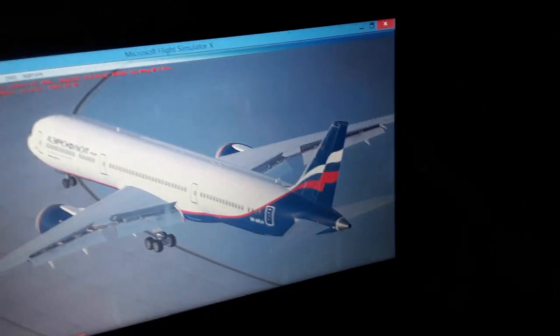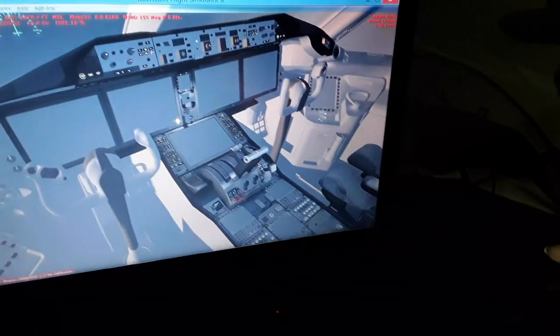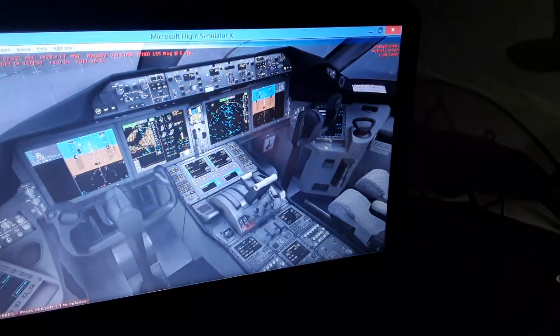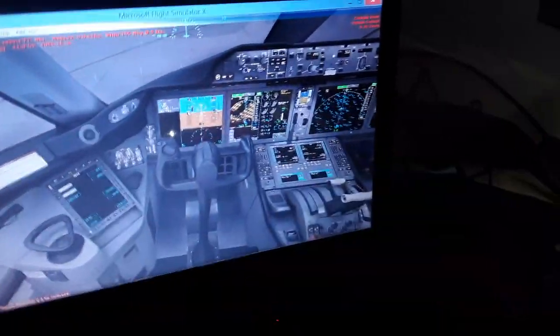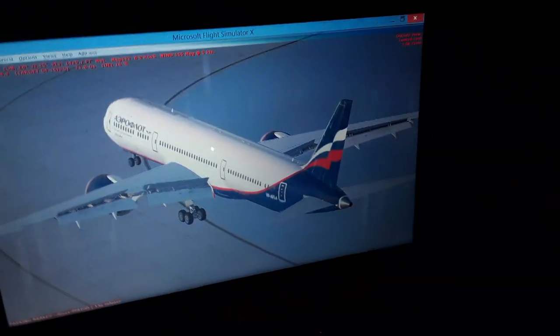In landing we have the inverse: first we have the rudder, then the nose wheel coming in as we slow down the aircraft. So this is a very simple explanation. You use the rudder pedals, which act both on the rudder and the forward nose wheel, instead of using the tiller. Also we have the toe brakes. We can press the brakes and stop the aircraft.